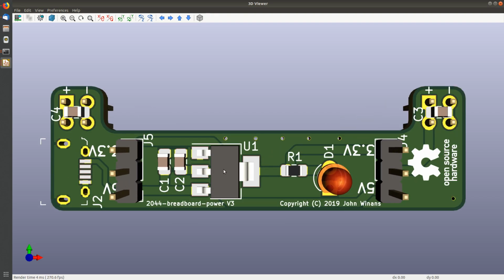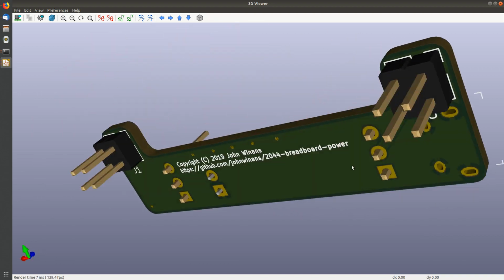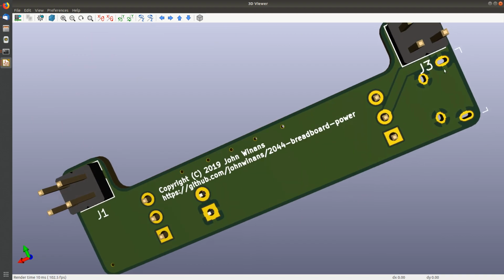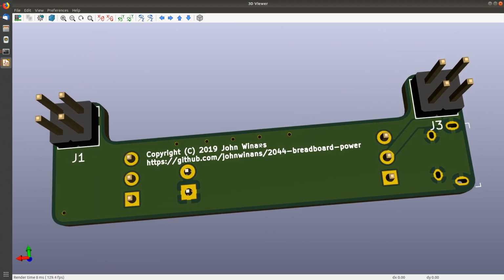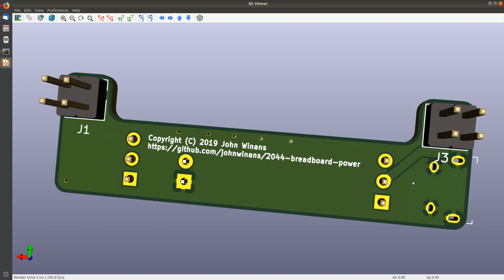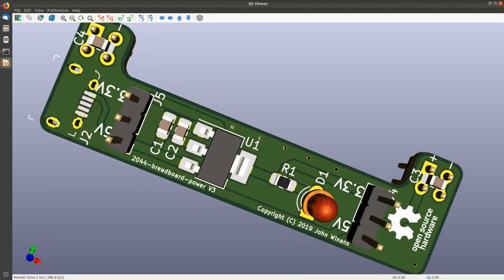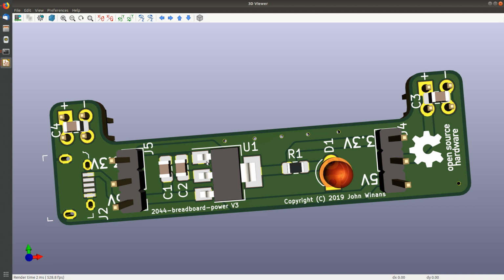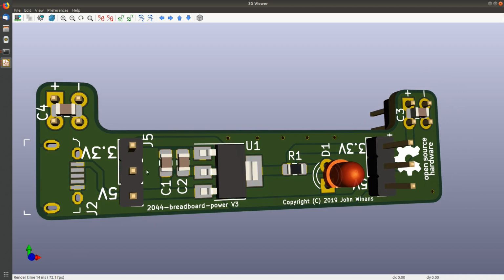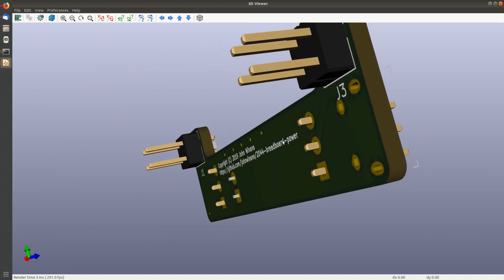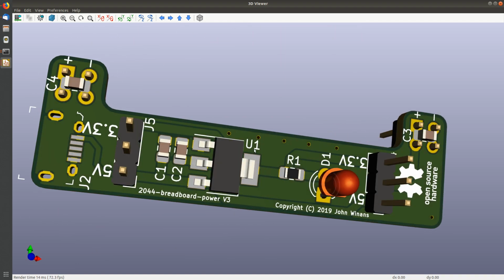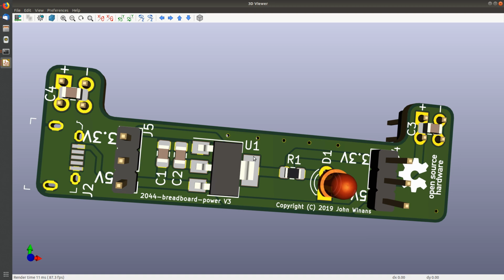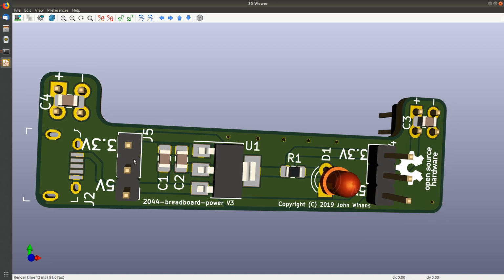And I think that's our final board. There's the bottom side track that we just put in there. No problem. Doesn't interfere with anything there. Looks pretty good. We shaved $2 off the PC board cost, probably, by shrinking it down. It's still going to be pretty sturdy. That just comes from you building a couple of boards, you know. You don't want to get so small the board snaps, but this isn't going to snap. It's going to be pretty robust.